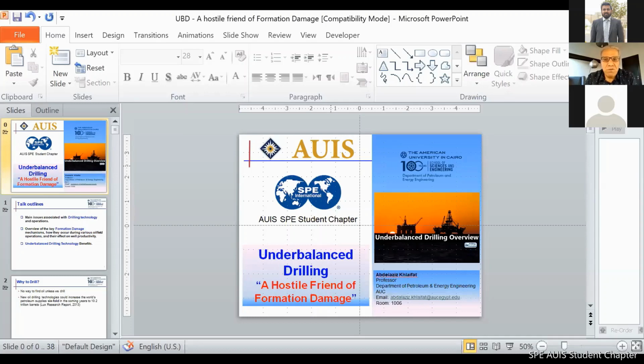But when it comes to offshore, we always have a problem with the footprint because underbalance requires some footprint. You need to have some facilities on the surface ready to deal with the produced oil and gas. Now, when you do overbalance, there might be no issue because we hit the reservoir, we don't produce right away, or we shut in the well. But with underbalance, because of the simultaneous production while we drill, we have to be ready for this. So this is another issue that we have to take care of when it comes to offshore.